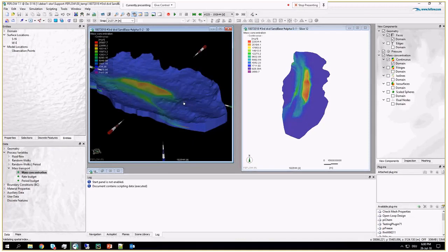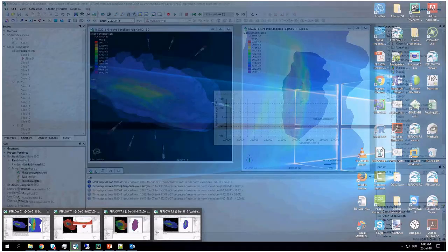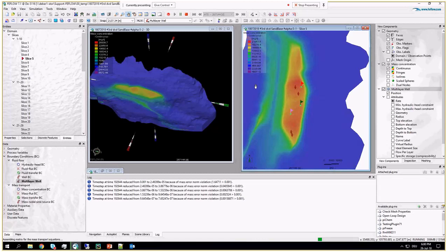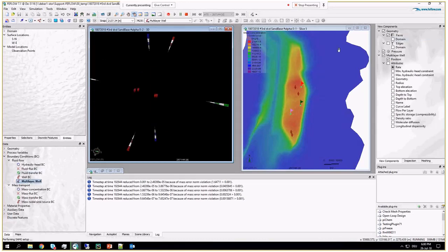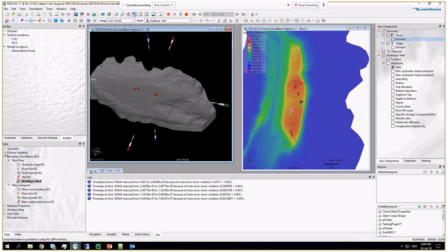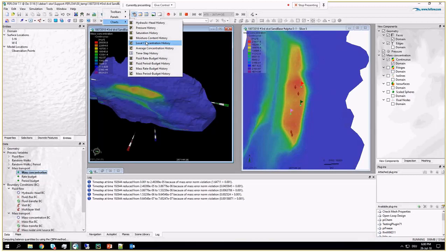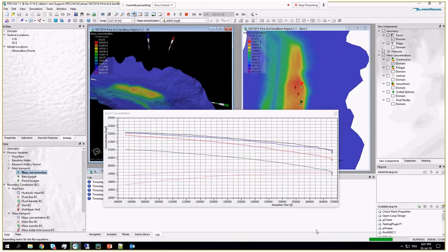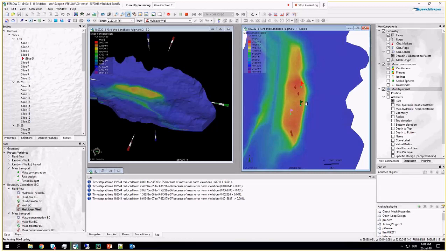And when you have the initial conditions of concentration, you can do an exploration model where you can basically start pumping out. So I put some wells in this last model. Let me show you the wells. So multi-layer wells here you see. There are just 4 of them, and you can monitor nicely the concentration in multiple locations in the system due to pumping conditions. So we can go to local concentration, and there is a decrease of concentration in certain locations. So here are my observation wells, really close to the vicinity of the wells.